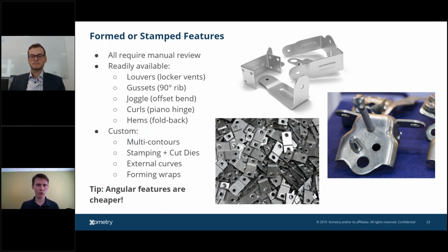And to make formed or stamped features, you need a die set. So these die sets are just like tooling, think injection molding. You are getting charged upfront for that tooling. It takes time to make that tooling, so you just added lead time to your project. And if you have low volumes, oftentimes my challenge with you is how can I turn this into angular bends for my low volume project or shift to a different material, because oftentimes the price and lead time may not add value to your project for low volume.